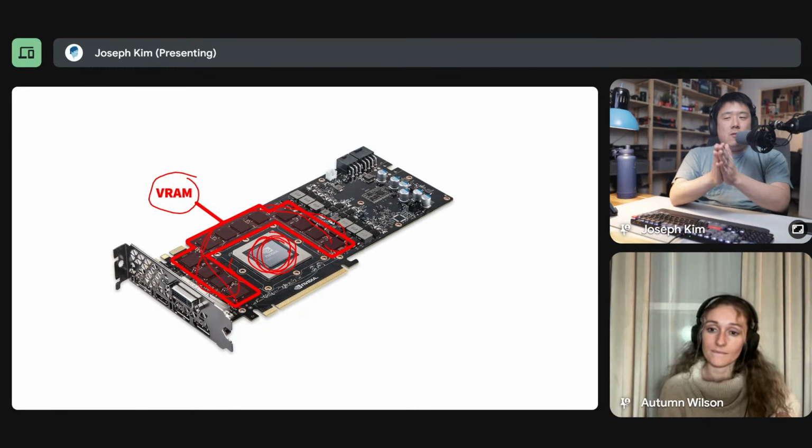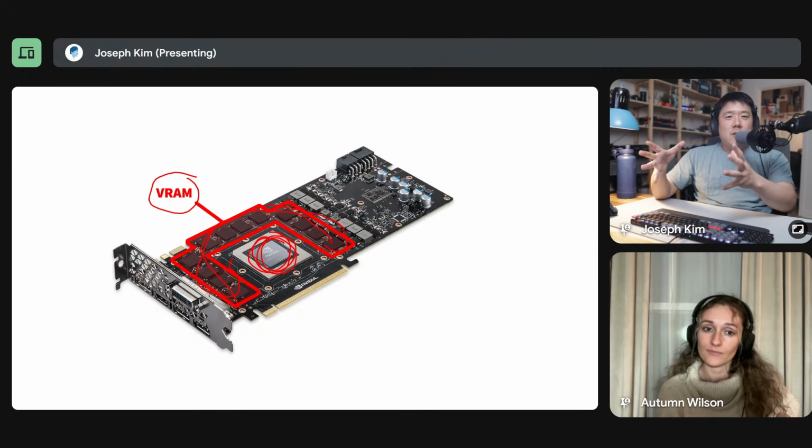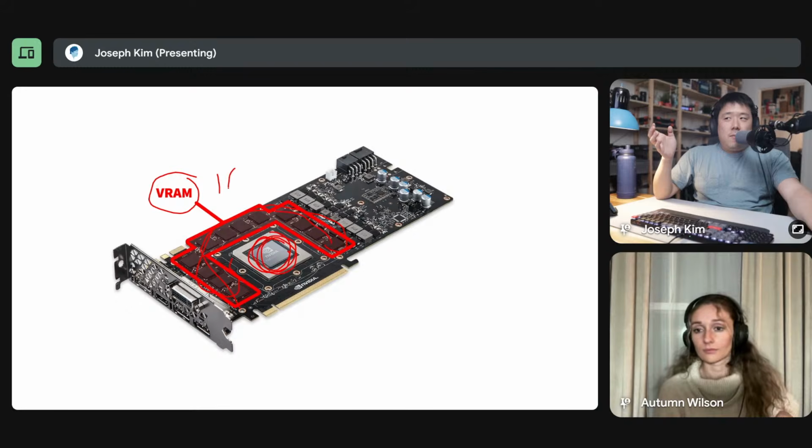So when you load a large Lumion model, for example, it needs to dump all of that model data on this tool belt, and that tool belt needs to be large enough to handle the complex geometry that you're bringing inside of Lumion. Lumion actually tells you how much VRAM you're using. For example, my graphics card has 16 gigabytes of VRAM, and the chances of filling that up are pretty slim.